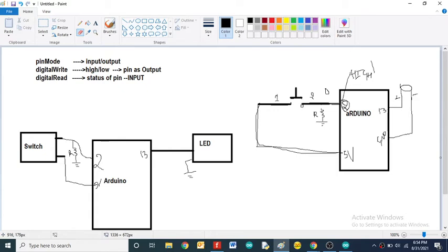There will be a magnetic flux line around this line, so a small leakage current is transferred to terminal 2. Then you will get a high level signal by default. For that purpose I will connect the resistor here. This is the pull down network. We have two types of network, pull up network and pull down network. So it is a pull down network. By default, if anything is there in this line, it should be grounded here. To avoid the leakage current, we use the resistor.